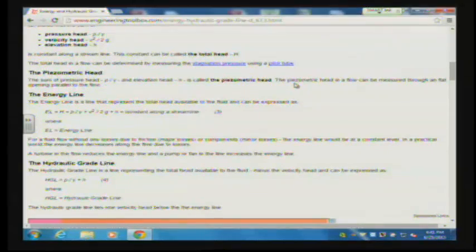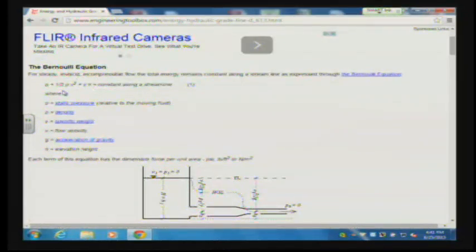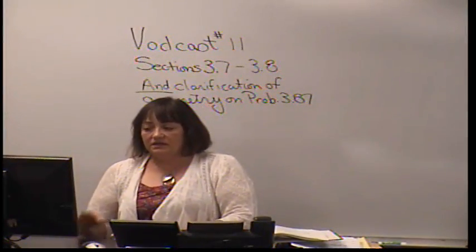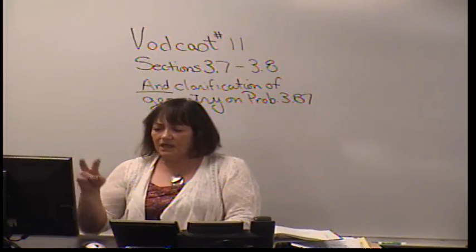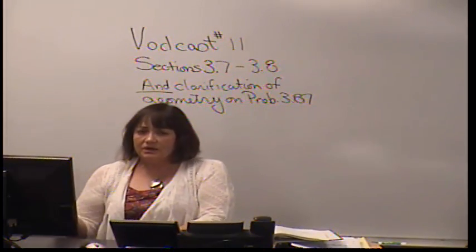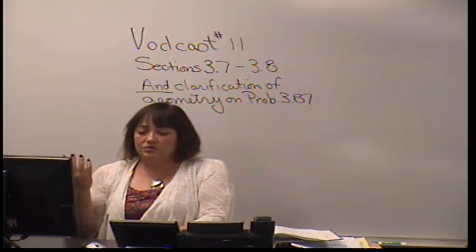So the piezometric head basically is the same as the hydraulic grade line. And it just describes here the piezometric head is the flow that can be measured through a flat opening parallel to the flow. That kind of a measurement, the flat opening parallel to flow, is called a piezometer. So anyway, one of the reasons I wanted you to see this is just because Engineering Toolbox is such a great site for quick refreshers of these different types of ideas, but also because I wanted you to see the graphical representation of the energy line and hydraulic grade line and what they mean. And it really is kind of that simple.